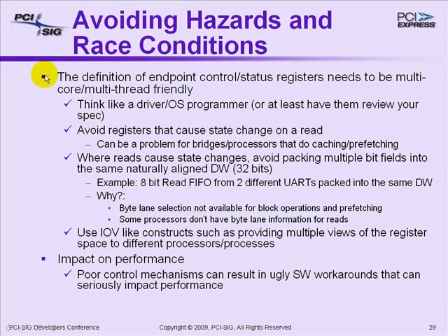Now, there are hazards and race conditions that you can end up designing into your endpoint device if you're not careful. With multi-core, multi-threaded processors and operating systems, this is even more critical. So in order to avoid this, you really need to think like a driver or OS programmer, or at least have them work with you to define what your register set and hardware-software interaction model looks like.